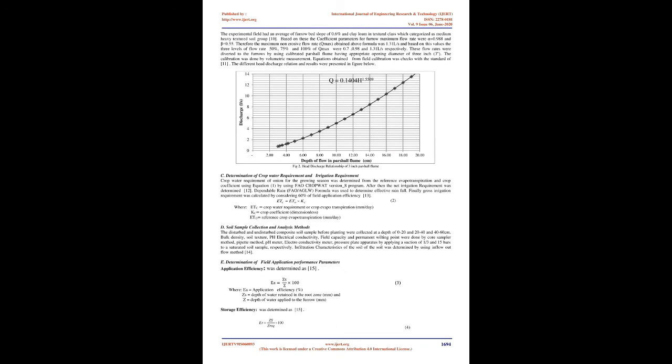Figure 1 below shows the monthly distributions of reference evapotranspiration, ETo, and effective dependable rainfall of the study area for 31 years, 1987-2017. The potential evapotranspiration of the study area calculated using the CROPWAT model is more than the effective dependable rainfall in most of the months, and in this case, rainfall is insufficient to compensate for the water lost by evapotranspiration. This indicated that most of the crops planted in these months need supplemental irrigation. The effective dependable rainfall is more than ETo during June and July, meaning that no irrigation is required during these months. B. Experimental design and treatments.